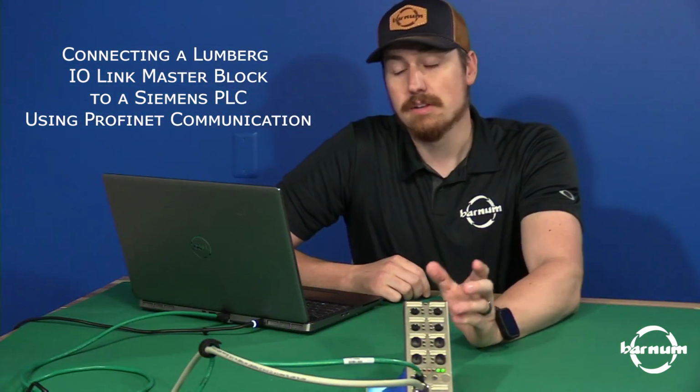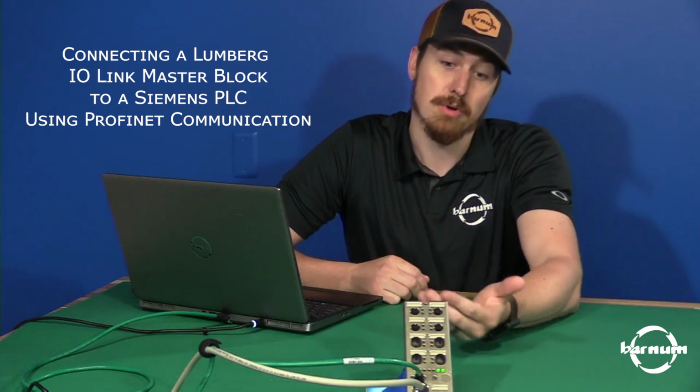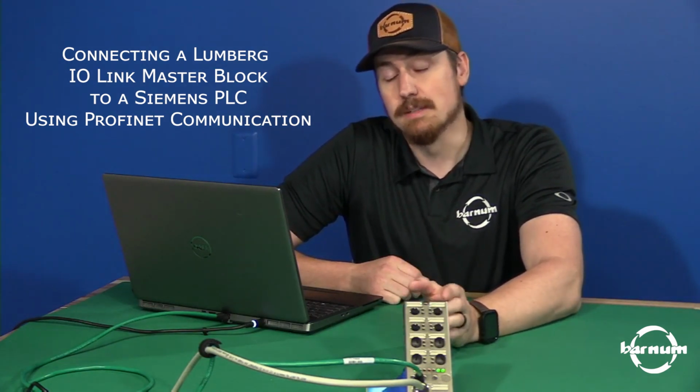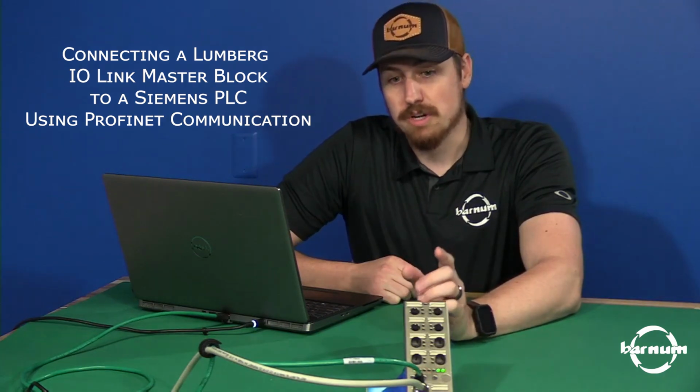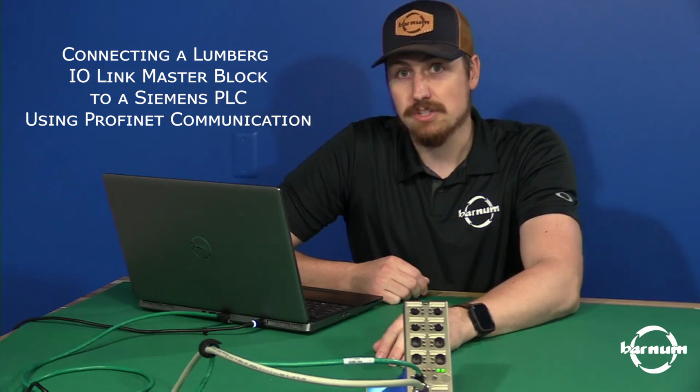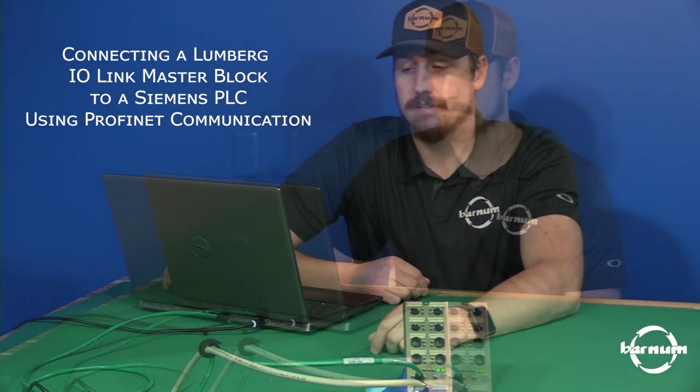Then, since we are going to be doing Siemens Profinet with this, we're going to take the first rotary switch and point it to the P, and then do another power cycle, and now this block is permanently set for Profinet communications until we do another factory reset.